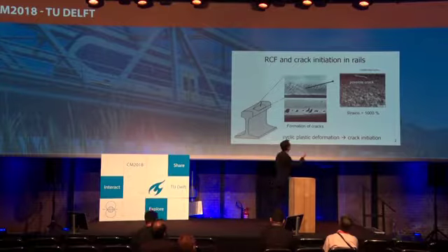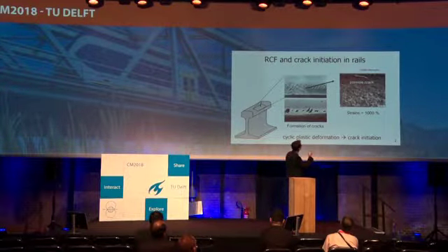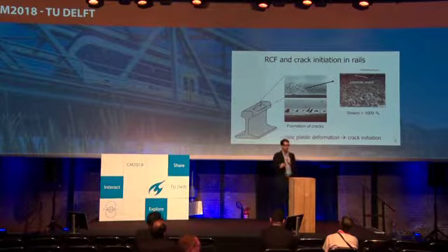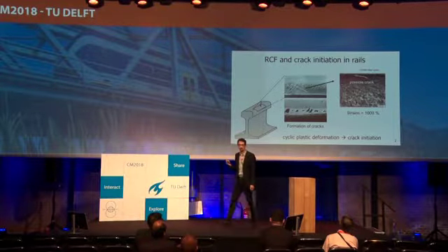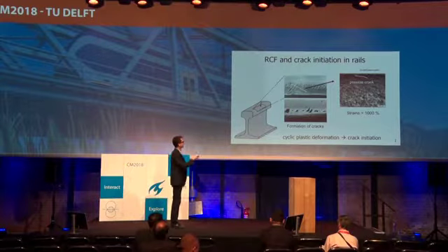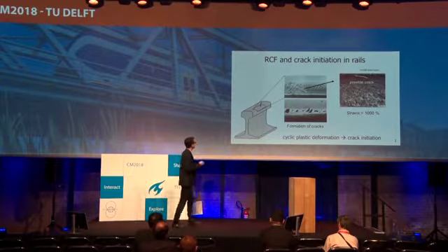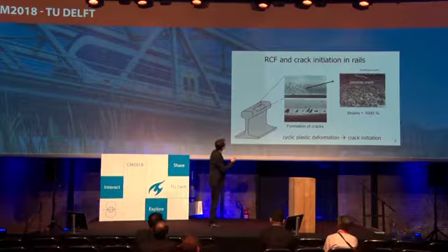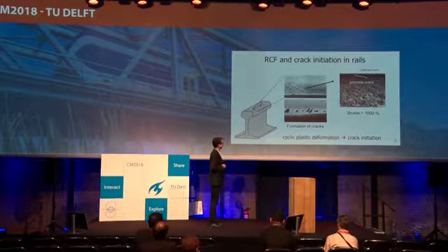So if we have a shear deformation field like that in the rail surface, those trajectories of the deformation more or less define also where the cracks will be. And on the other hand, when we reach a certain shear strain up here, that might also be an indicator or even a damage criterion. I think if we talk about ratcheting and failure due to ratcheting, that's something like that. So those are two cracks. There could be some head checks like that. There could also be some breakouts.